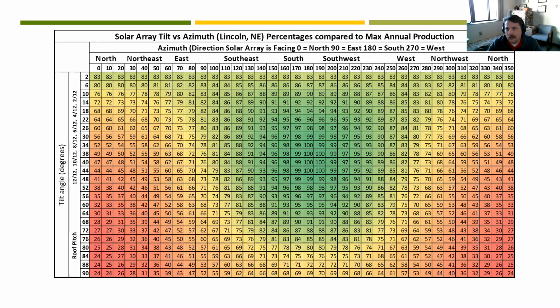Because if you've got a roof that's 25 years old, you don't necessarily want to put solar on that roof and then have to, in 10 years, if let's say the life of a roof is 35, it could be different for each roof. But if you only expect it to last 10 more years, then you're going to need to take that solar back off to tear the roof off and put a new roof back on. So it's good to coincide that with either a roof replacement or a roof that's in very good shape. That's an important consideration.